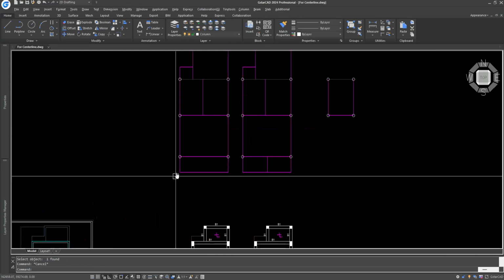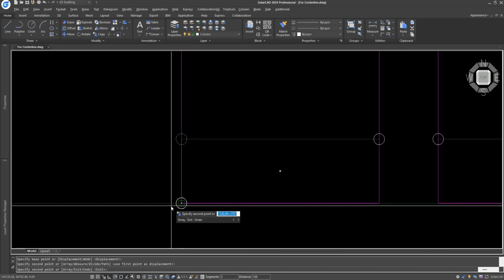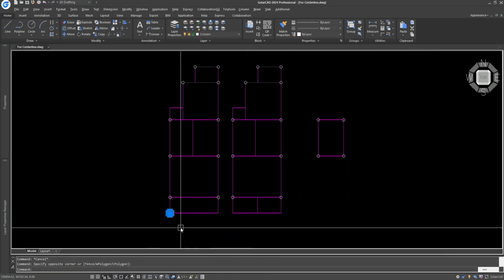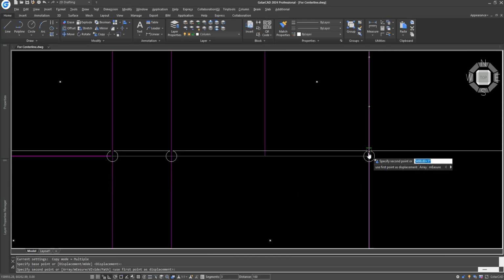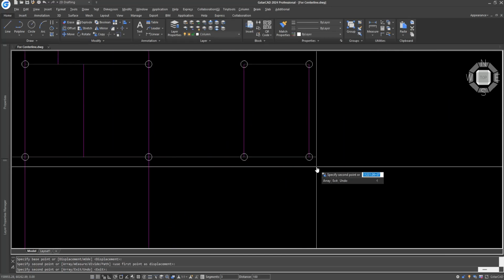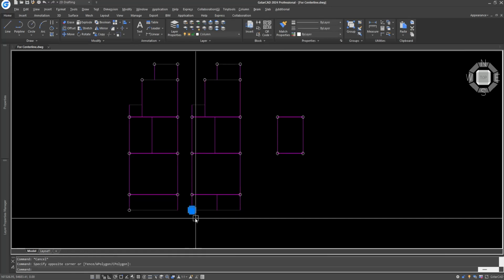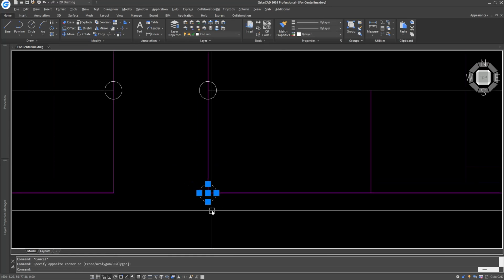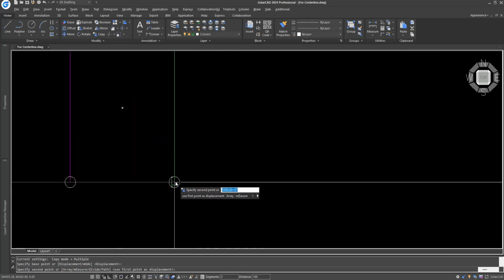Now this is our reference point, so just put 1 column at the reference point, that is 0 0 0, because you need to have a fixed 0 point so that all the plans comes in line, right? This point has come wrong. This is perfect. Yes, let's just copy this to stair cabin also.